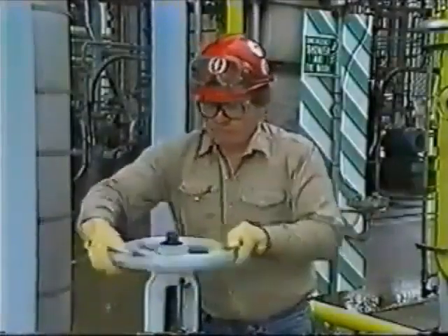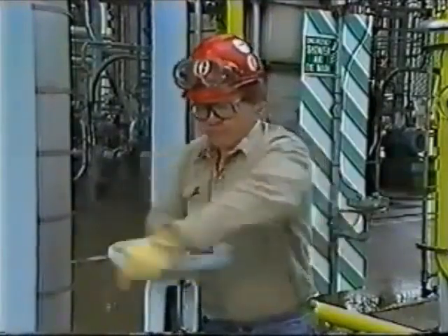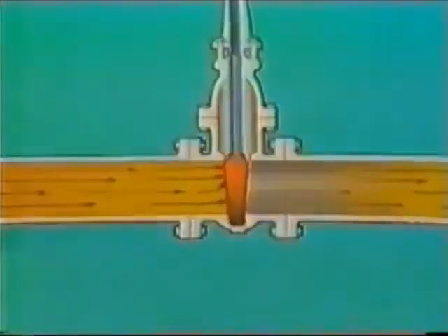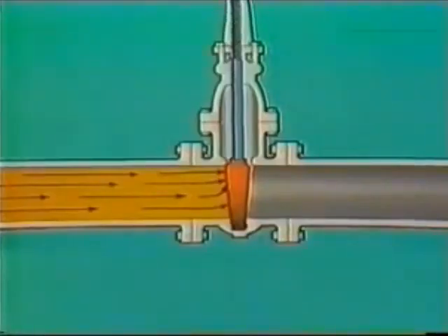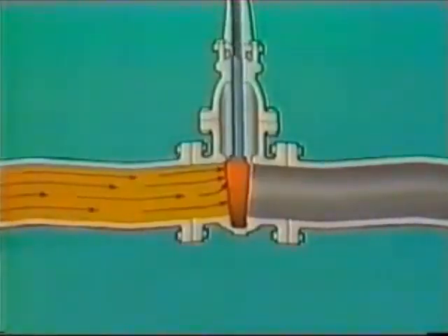Regardless of what type of valve operating mechanism is used, valves should always be opened and closed gradually. This will prevent sudden pressure and temperature changes from occurring in the piping. For example, if a valve is suddenly snapped shut, the abrupt change of flow causes pressure surges that can damage the valve and, in extreme cases, even rupture the pipes. This is known as hydraulic shock and is primarily a problem in lines controlled with quick opening valves.